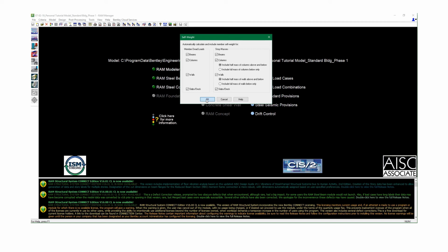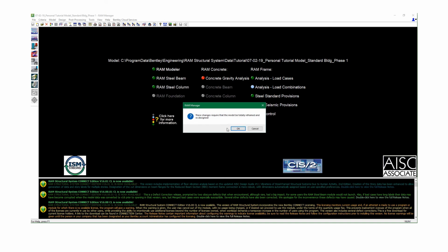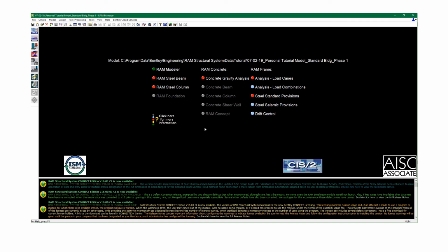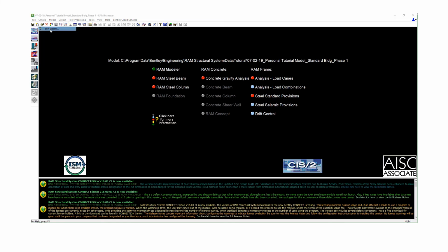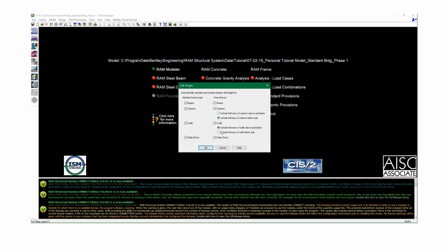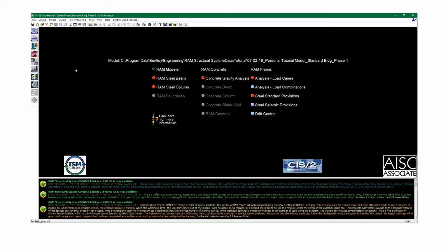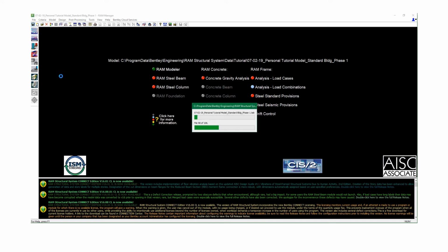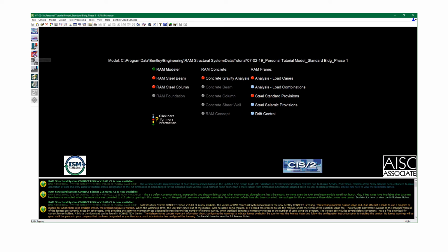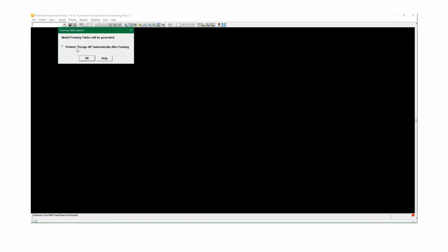All right. So anyway, we will modify this to half up, half of the columns above and half of the columns below included. Say okay. I get that warning. Once again, I'll go back real quick just to make sure that we see what this thing was telling us. Hopefully it actually happened. It pops up, but it basically was telling me it has to redesign. Okay, so that was our one shot since we changed it. Since we had to redesign, we will redesign here, gravity and lateral.